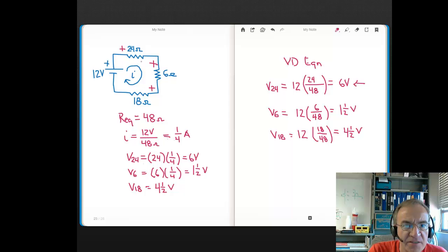So there's constant flow here. Well, in order to maintain that constant flow, it makes sense that the largest opposition would have to have the most pressure, right? So to maintain that constant flow, our largest resistance has to have most of the voltage. Okay, and likewise, the smallest resistance would need a smaller amount of pressure to maintain that constant flow.